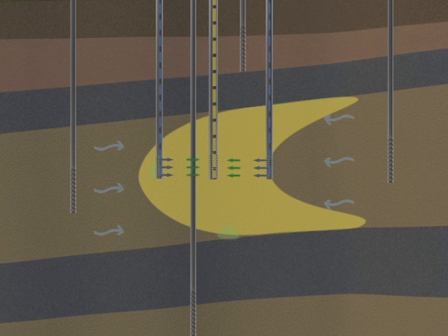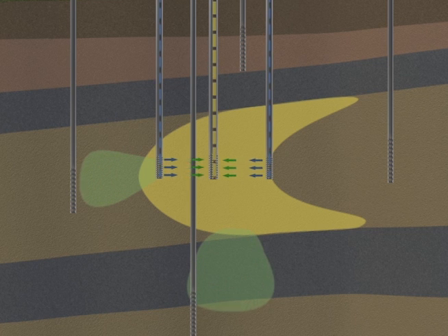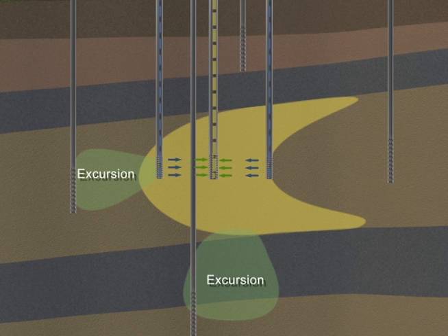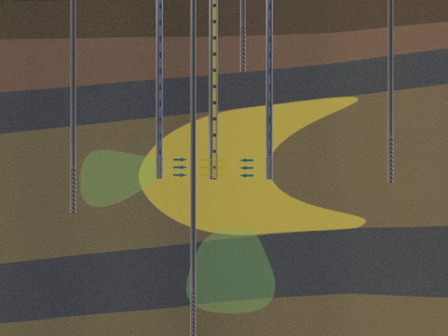A detection of impacted groundwater outside the well field in the exterior monitored wells or in the overlying and underlying monitor wells is known as an excursion. If either a horizontal or vertical excursion is detected through monitoring, the injection and extraction rates can be adjusted to hydraulically pull back the excursion before it moves outside the aquifer exemption area.